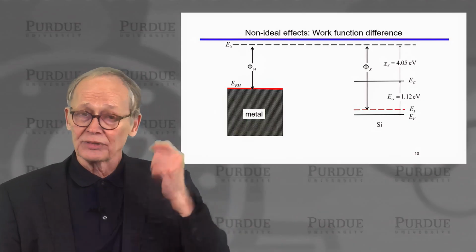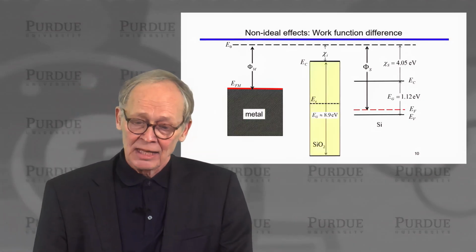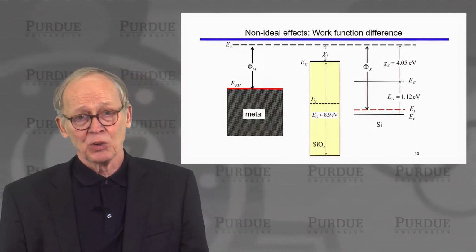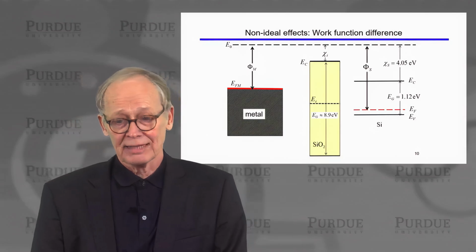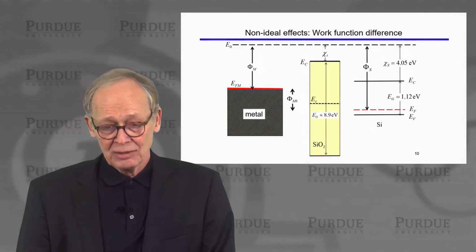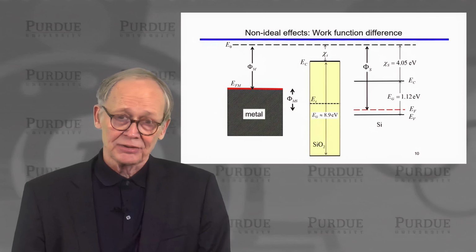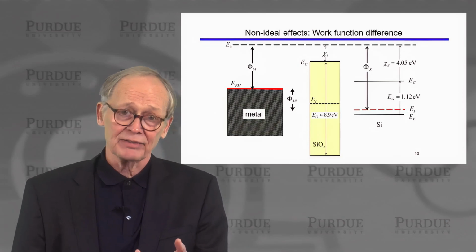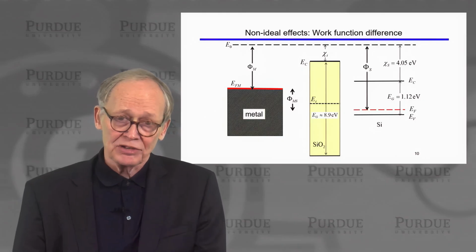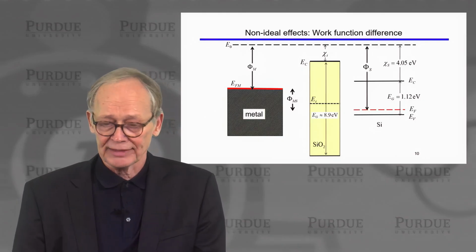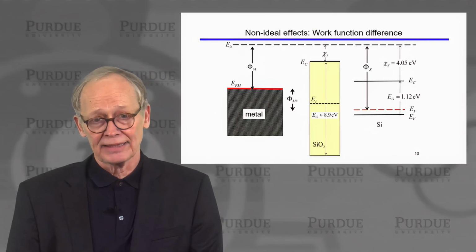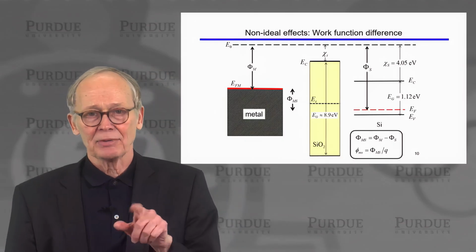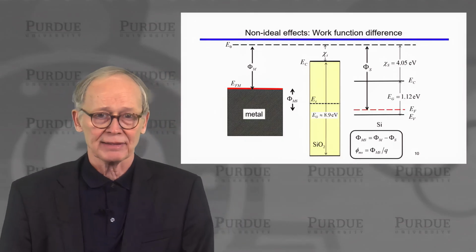And the chances are those two work functions are not going to be the same. When we put this metal, insulator, and semiconductor together and we're in equilibrium, there has to be one Fermi level constant everywhere. How is that going to happen? Well, that happens because a positive potential develops on this gate, a built-in potential, even in equilibrium, which lowers the energies in the metal gate, pulls this Fermi level down so that it aligns with the Fermi level in the semiconductor. So that metal-semiconductor work function difference, capital phi sub ms in joules or expressed in electron volts,